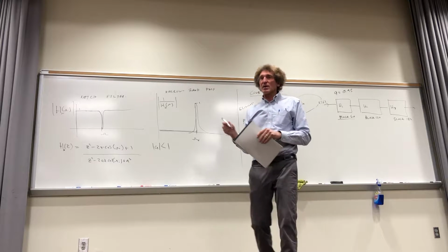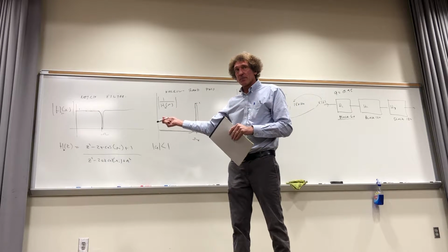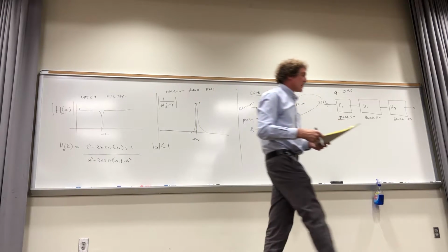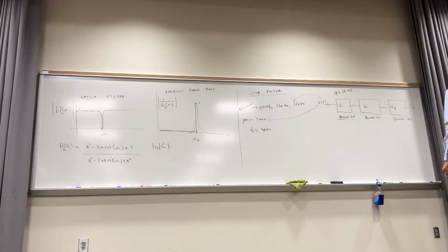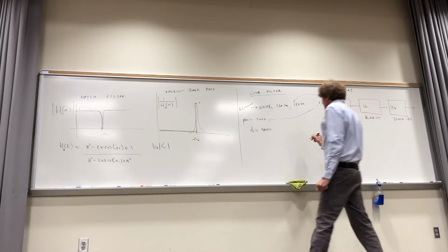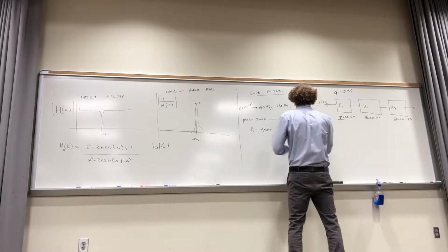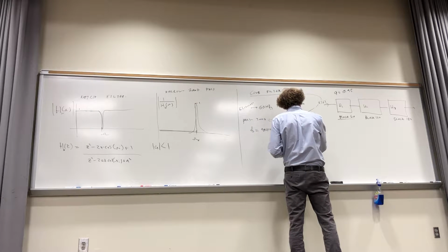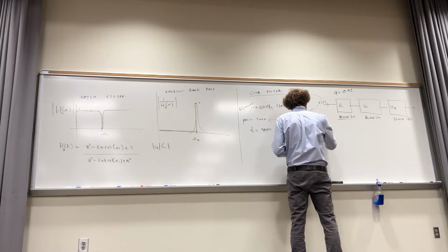All right, so if I'm just going to do this one, I want to create a standard notch filter to block that one. Let's do it this way, all right? If I'm going to create a standard notch filter for that one, we just did this. What do I do? Remember the steps? Well, I want to block what? 60, right? So I want to stop 60. So I want to block 60 hertz.